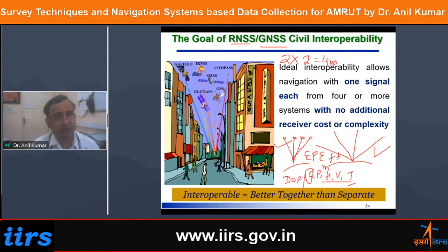What we can do in the ground is give some time, say a few minutes after switching on the machine. Just after a few minutes, it establishes the connection with the GPS signals, and the DOP becomes stable. Around 1.5 to 2 or 1.8 you can get if it is an open area. If you record your points at that time, the accuracy will remain very good.